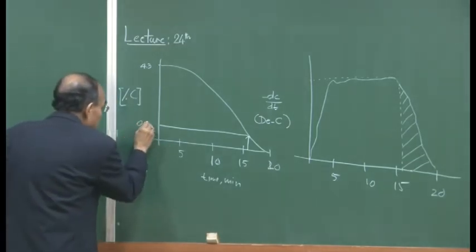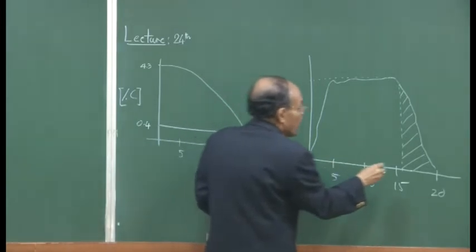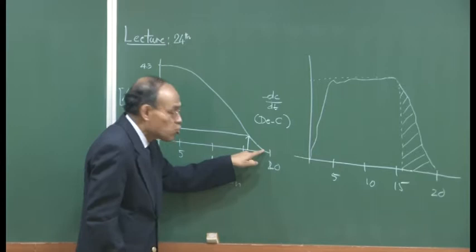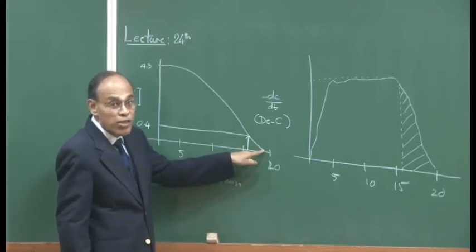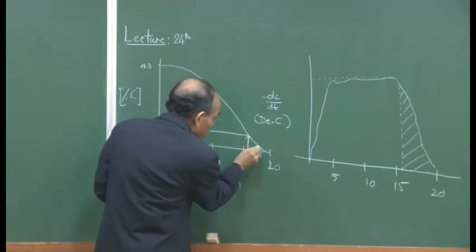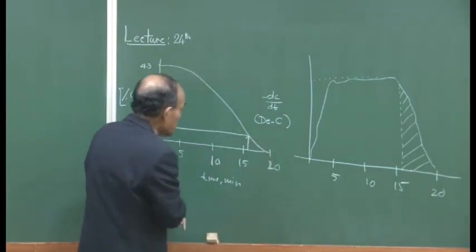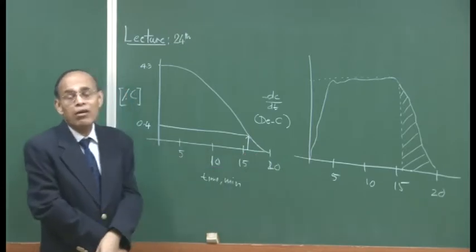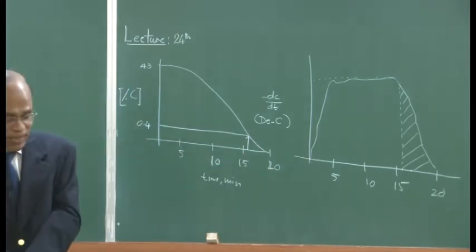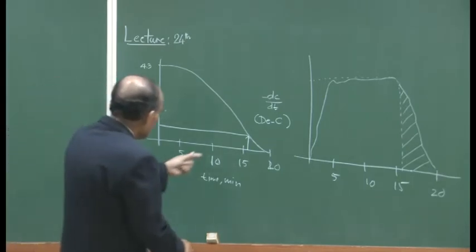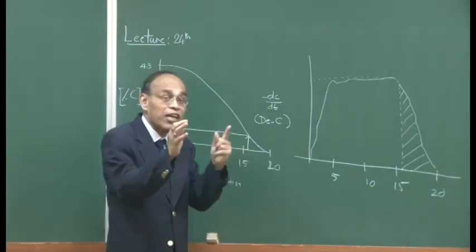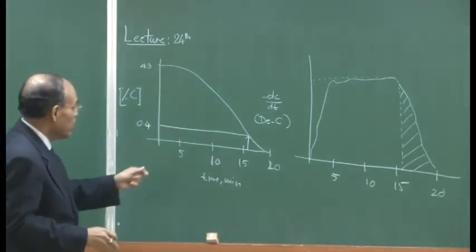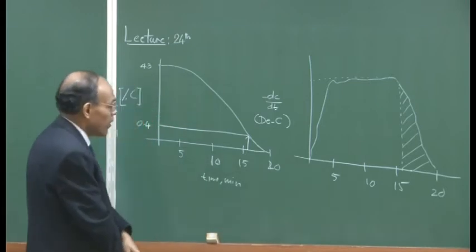And then sometimes you may have to stop at 0.1%, and this point needs to be controlled. So, your ability to predict this curve precisely in this particular region matters; you cannot afford to do experiments for every heat, and establish that for this grade of steel this is my curve, and then adapt that curve to the making of a particular heat.